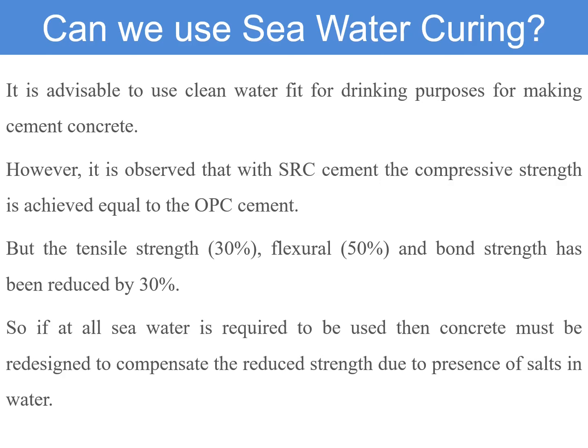So it is advisable to use clean water fit for drinking purpose to cure the concrete. However, it is observed that with SRC cement, the compressive strength is achieved equal to the OPC cement when cured with seawater, but the tensile strength is reduced by 30%, flexural strength is reduced by 50%, and bond strength is reduced by 30%. So if at all seawater is required to be used, then concrete must be re-looked at, must